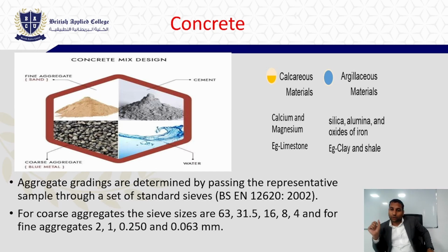Now how you will use this dry volume is, you need to know the grade of concrete. Suppose you are using M15 grade. For M15 grade the mix ratio is 1:2:4. The basic grade M15 is 1:2:4. That means 1 part of cement, 2 parts of sand and 4 parts of aggregate. So that you need to remember: 1 part of cement, 2 parts of sand and 4 parts of aggregate.